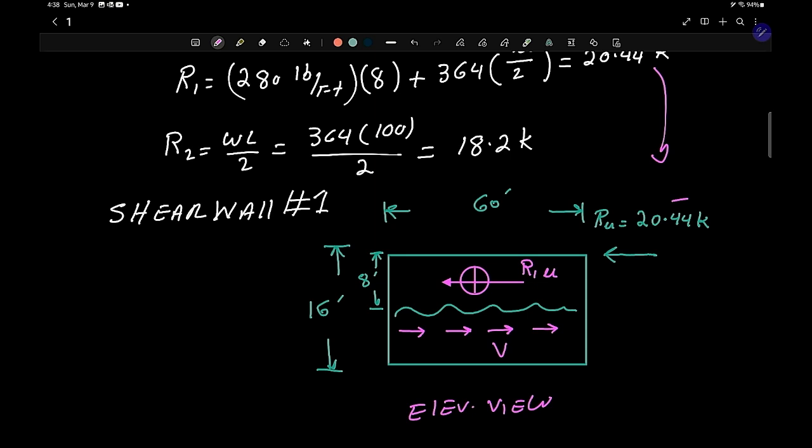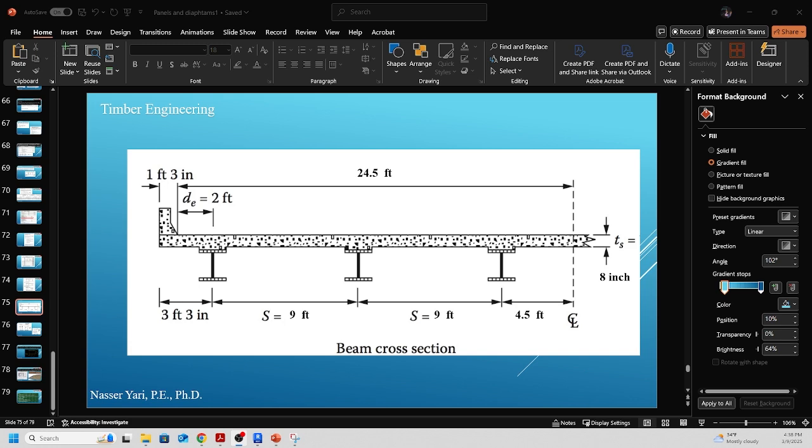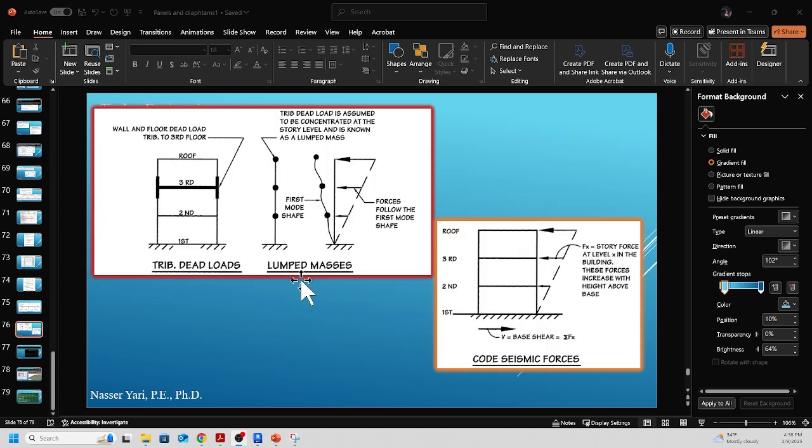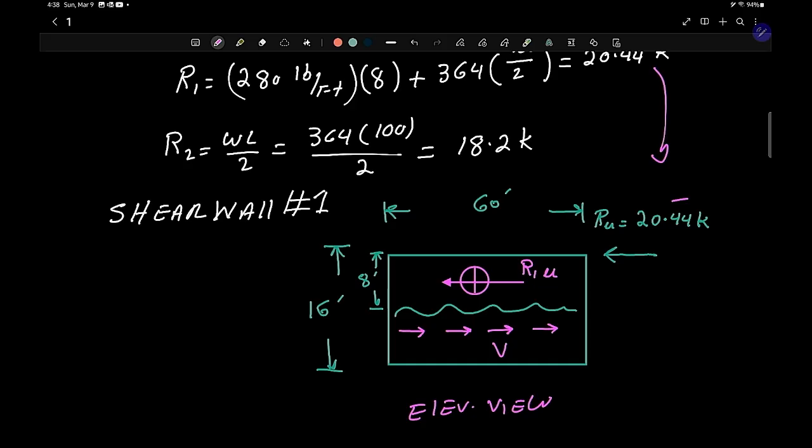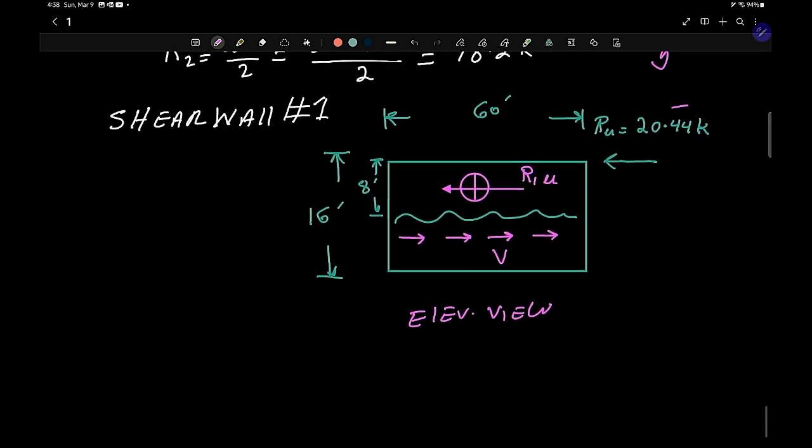The dynamic theory, let me go to the PowerPoint and show you something here. When you have a seismic force, when a building shakes, the weight of the building becomes a liability, becomes sideways forces. As you can see here, for the diaphragm right here, they're going to use the tributary width to be right here, halfway. Anyway, let's go back to the problem. We're just going to stick with the halfway for now, rather than the entire wall.